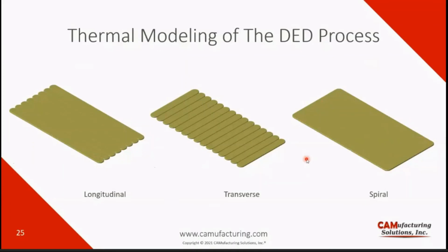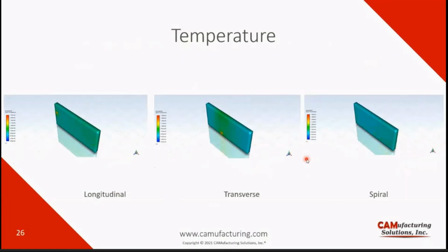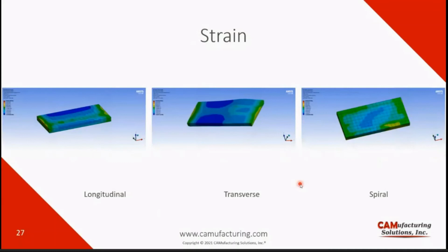Doesn't it matter which one we use? Of course it does, and we are going to show it. So this is a temperature versus time graph for all three different toolpaths. You can see over time, that's how it is simulated, the temperature of every element of the block. And what would the result be? So this temperature would affect the stress and strain. So our R&D team members, they calculated the temperature, they simulated the stress and strain in X and Y direction. So the next slide I'm going to show is the X strain of all the three blocks while doing the deposition versus time.